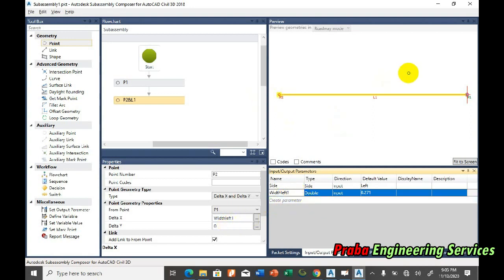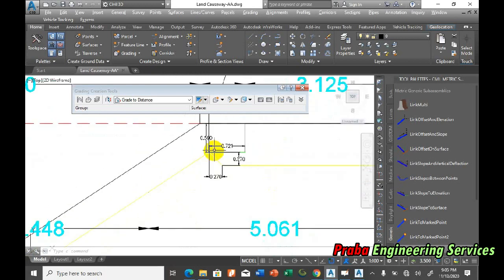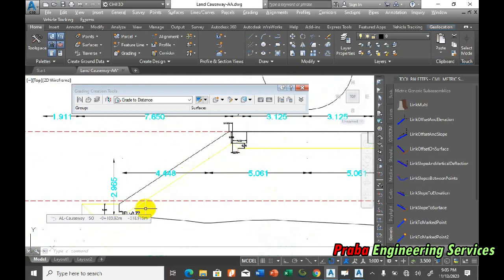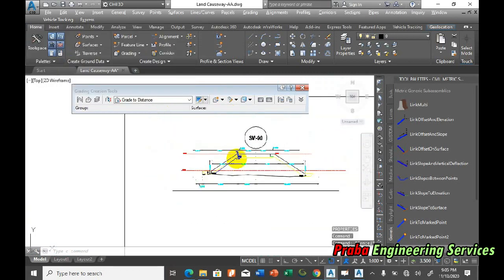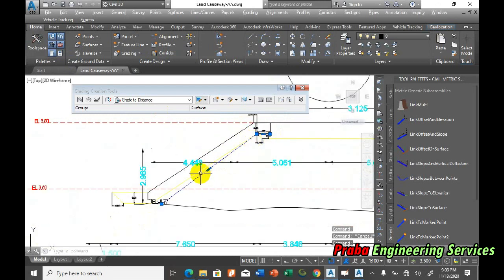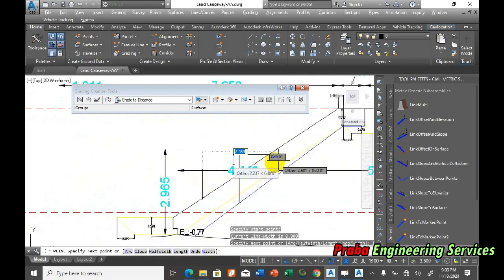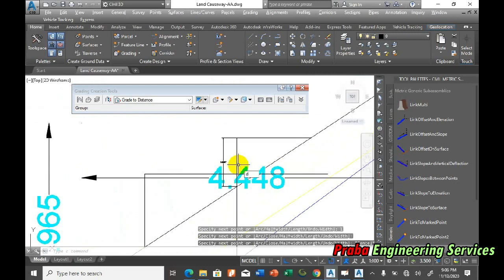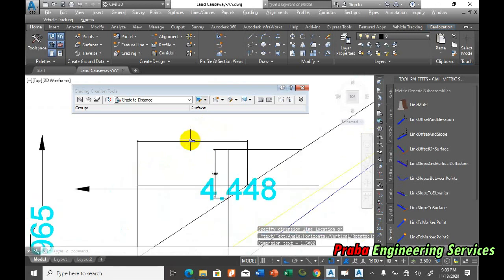Okay, the next step is another point. This one I want to build first, from here to here, and go down, go to surface. I want to make a line. All right. Okay, this is one step. I already get on the top, and then I want to go another from this one, enter, and this one. 1.5 by 1. This is horizontal slope 1.5 by 1.